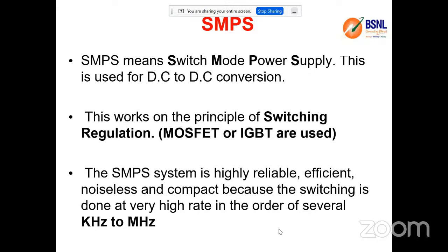As I said, if I need only a limited amount of current for this time, I can use one module. If I need more load, I can increase the number of modules based on my requirement. Such flexibility is available in the SMPS power plant. The idea is that here we are using MOSFETs and IGBTs. These are different types of transistors, which are semiconductor devices.